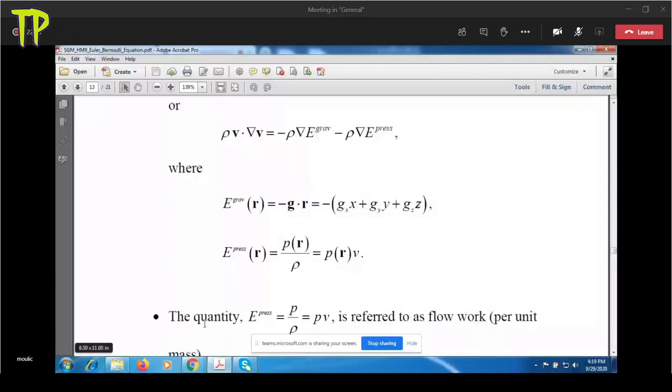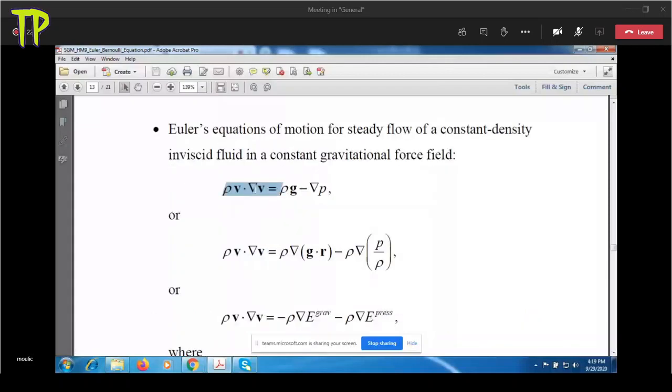In the case of a compressible flow, suppose I take this vector equation and take the scalar product of each side with a displacement vector dr, which may represent the displacement of a particle. Then if I multiply rho g dot dr by dv, rho dv into g dot dr will be the work done by gravity.